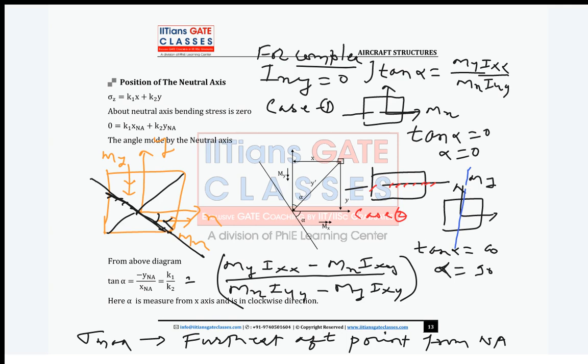So guys, if you go into industry, mainly private industry, everywhere people will ask you questions from this part. For any job, if you go for Collins Aerospace, Airbus, or Boeing in aerostructures, they will ask: sir, in simple bending, where is the bending stress maximum? Again, at the furthest point from the neutral axis. What is the furthest point? It is the top or bottom, right?